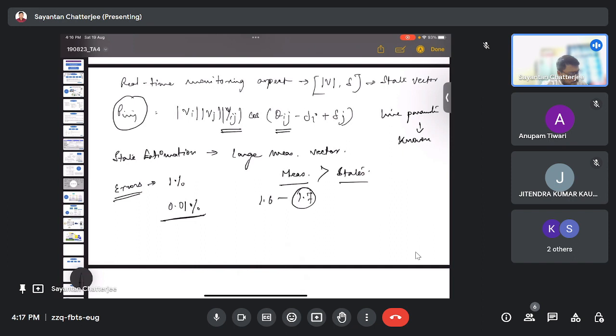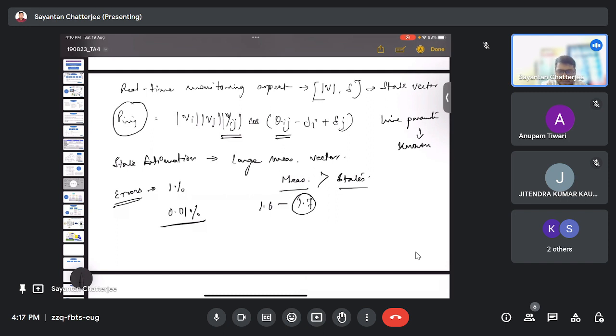So for this purpose, the wide area monitoring system gives the advantage over the RTU based, SCADA based system, with higher accuracy as well as a direct linear combination of the measurements with the states. Hence this technique is recommended for the future EMS system. But the problem is that the cost of these technologies is quite high, and hence this can't be directly implemented in the present scenario.